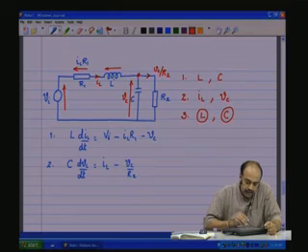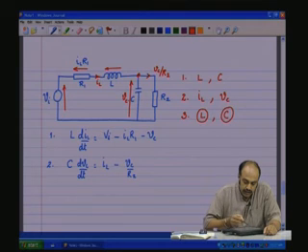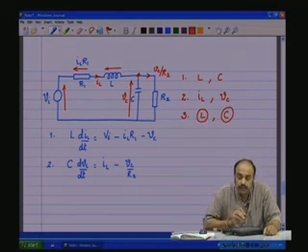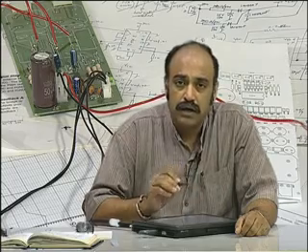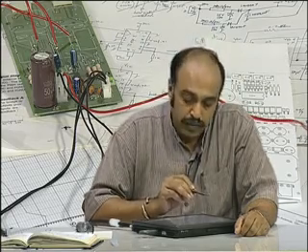So, for the inductor you are applying the KVL to get the voltage across it, and for the capacitance you are applying the KCL to get the current through the capacitance. With these two, you have defined the dynamic behavior of the entire circuit just in terms of these energy storing elements, the input elements and the parameters of the circuit. And this process is valid whatever the complexity of the circuit and whatever the domain, whether electrical, mechanical, hydraulic, or magnetic, and so on.